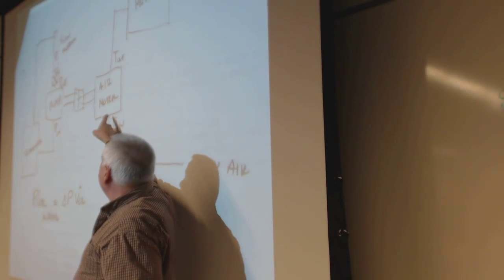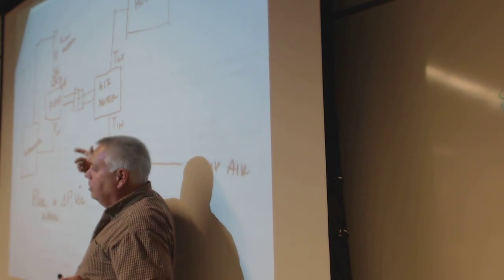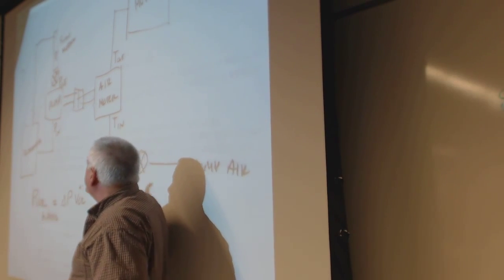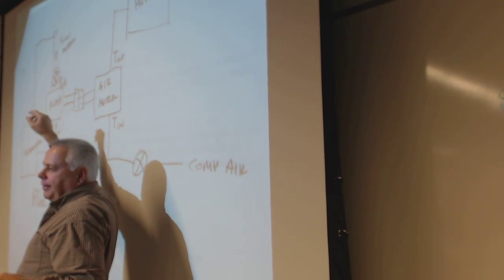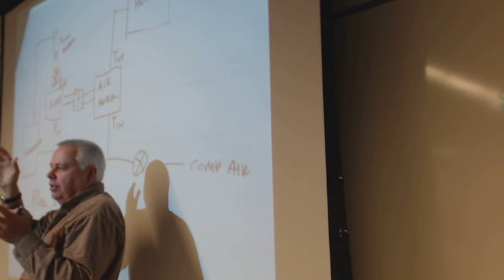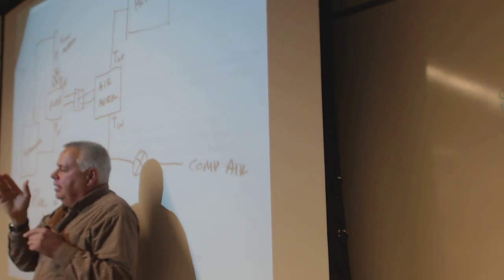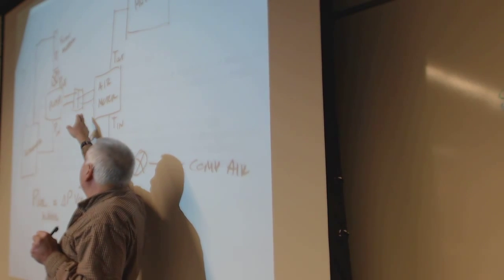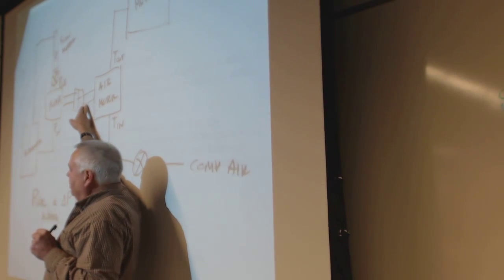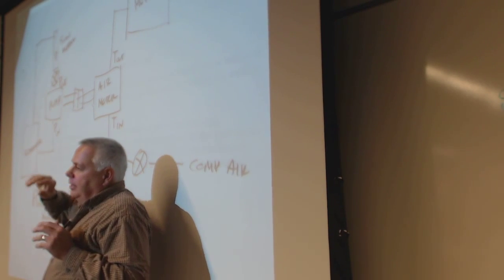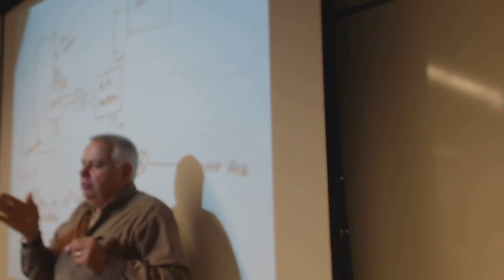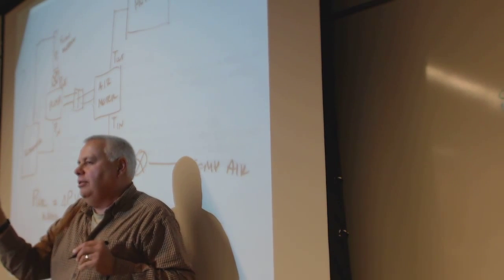It takes time for this to settle into a new load, so if I tell you 900, then you're at 880 to 920, but you have to make sure that you record exactly what the RPM really is. Because that's a crucial point.